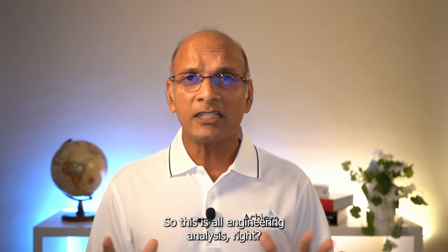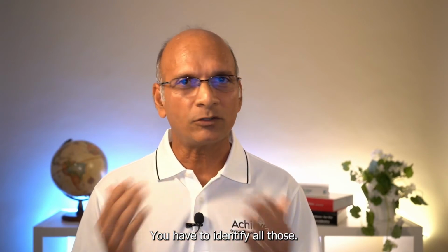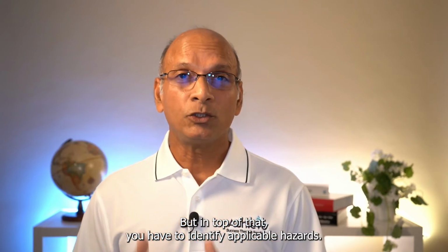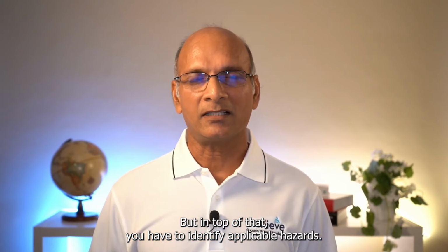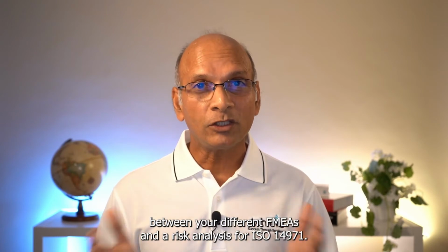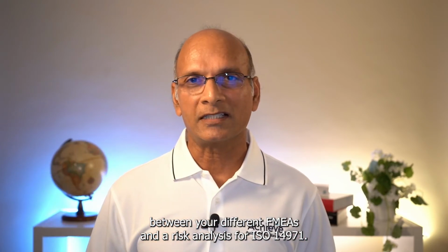So this is all engineering analysis, right? Local effect, you are right, local effect, system effect, you have to identify all those. But on top of that, you have to identify applicable hazards. And that is where I think you can find a connecting point between your different FMEAs and a risk analysis for ISO 14971.